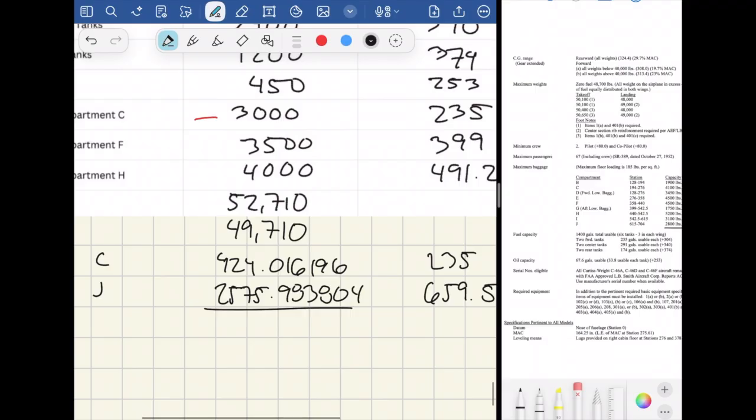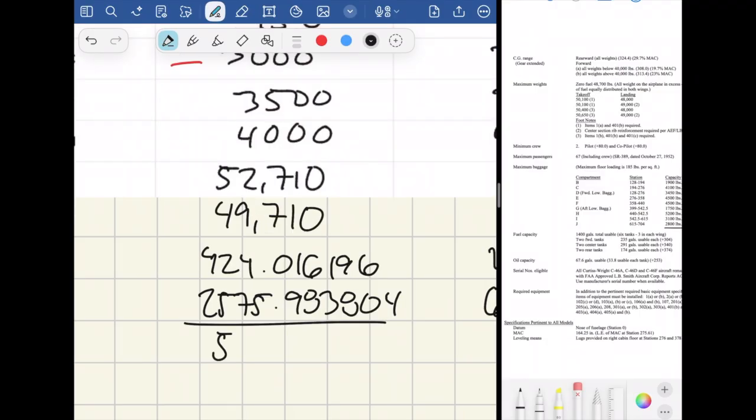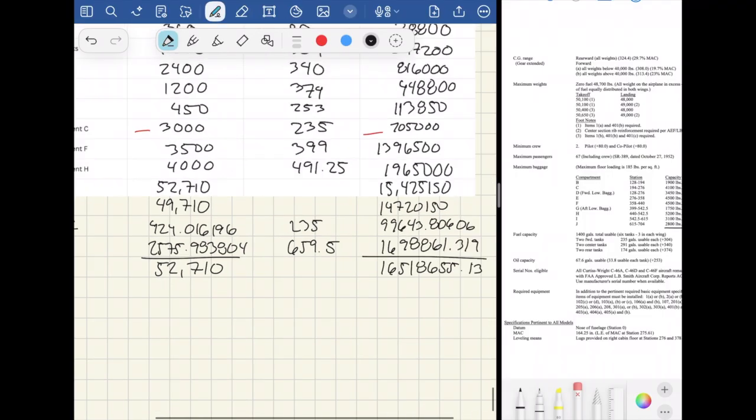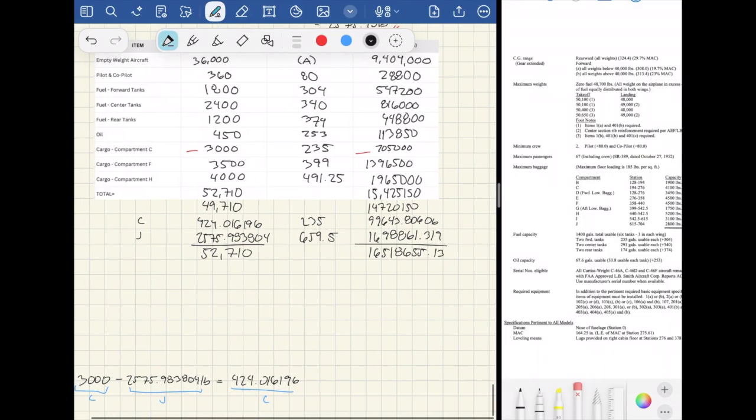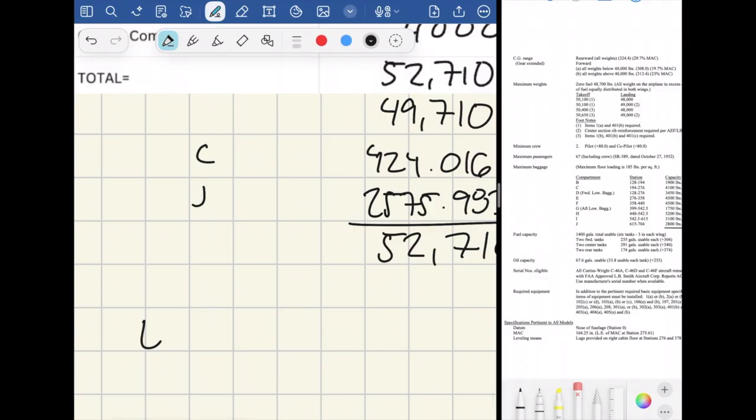And then for our total weight, so see guys, wala siyang pinagbago kapag weight. We just did this para ma-visualize natin. So now we're gonna solve for the loaded CG. Again, the loaded CG is equals to the summation of moment over summation of weight.